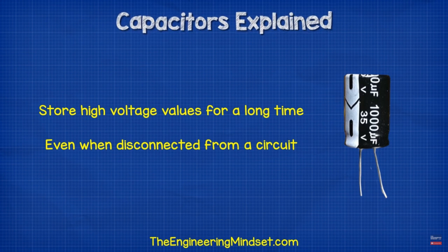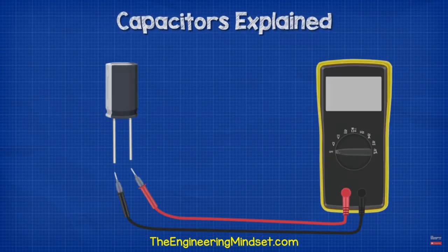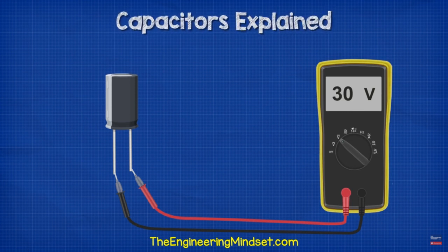To check the voltage, we switch to DC voltage on our meter, and then we connect the red wire to the positive side of the capacitor and the black wire to the negative side. If we get a reading of several volts or more, then we should discharge that by safely connecting the terminals to a resistor and continue to read the voltage. We want to make sure that it's reduced down into the millivolts range before handling it, else we might get a shock. To measure the capacitance, we simply switch the meter to the capacitor function.